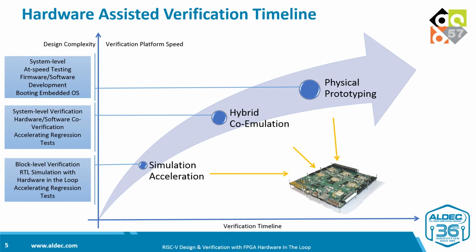Physical prototyping is the last pre-silicon verification stage. Again, the same FPGA board can be used to implement and run the entire SoC hooked with external peripherals and devices. Prototype implementation is optimized for speed, and so it's capable of running a complete software stack, including operating system, device drivers, as well as top-level user or device main application.